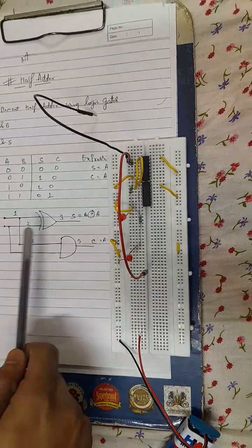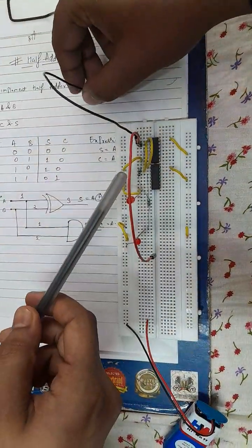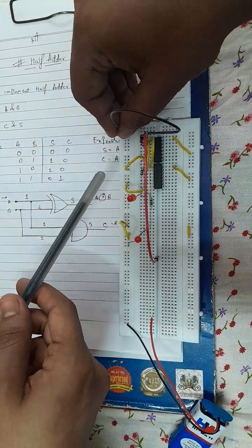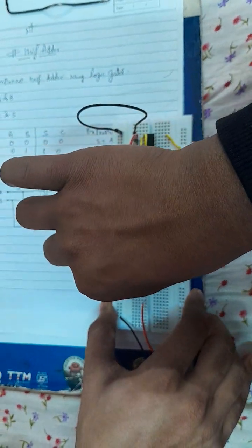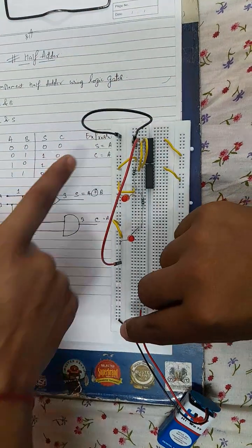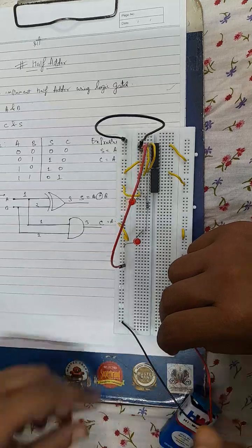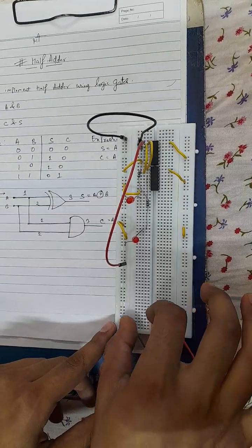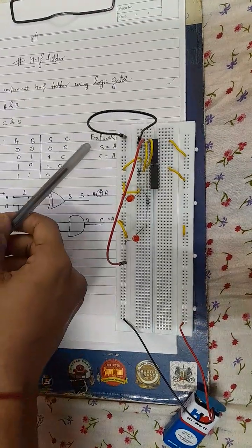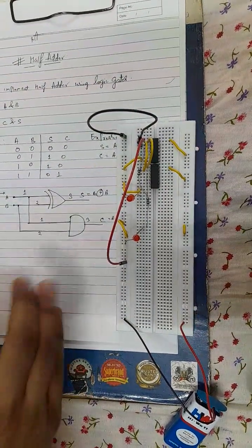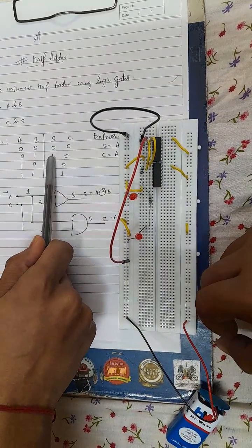We will now try to visualize the output. As we have discussed earlier, this is A and this is B. My teammate will connect them to the ground for the 0 case. So both inputs A and B are connected to 0 0. Now we will see the nature of S and C. As you can see, the power is now given to the breadboard, but after connecting A and B, both the lights are off. So both S and C are 0 0, depicting the 0 and 0 case.